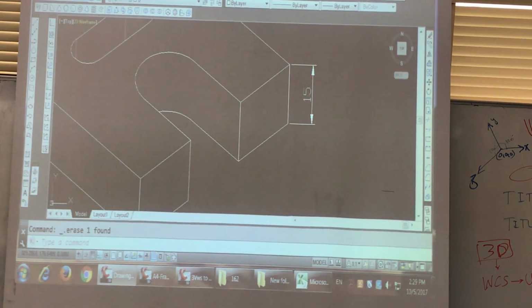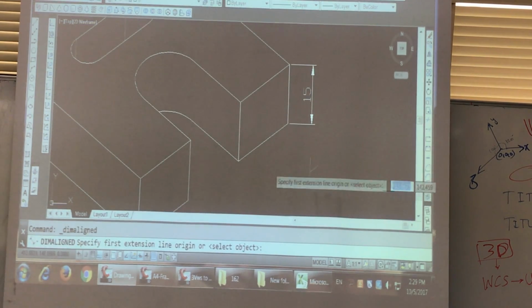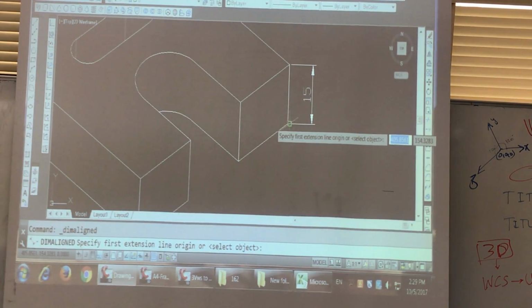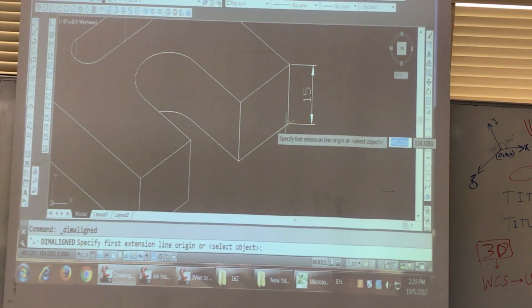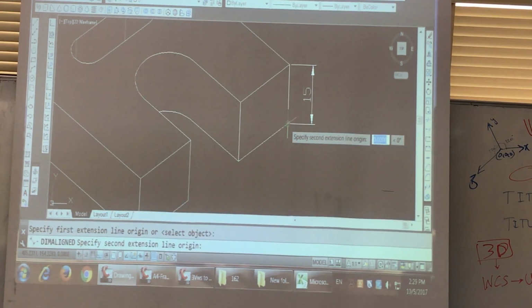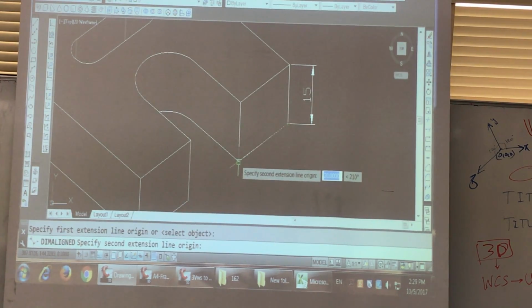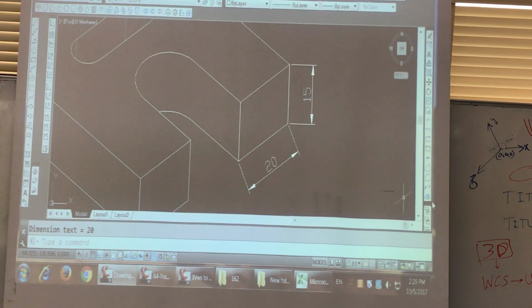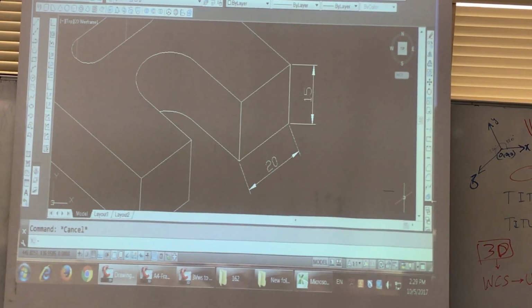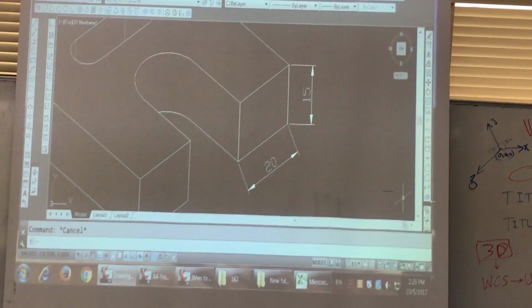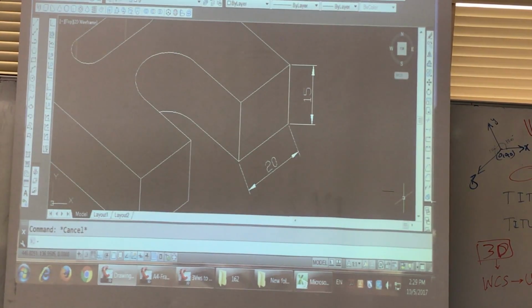See, when I use dimension, align, you have to click this corner correctly. I clicked here. Is it correct? No, it is here. This cross, isn't it? This is the one. From here to here, you see how much? Exactly. So while doing this, this happens. And the students do it 2-3 times, and they start coming to me saying, no, I did it 3 times, but it is giving 20.2 to me, 20.3, not 20. So just try to keep it in mind.